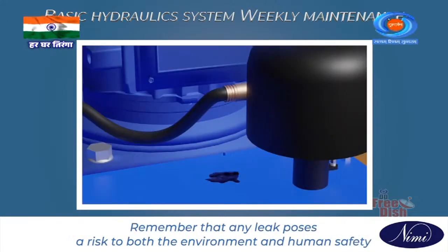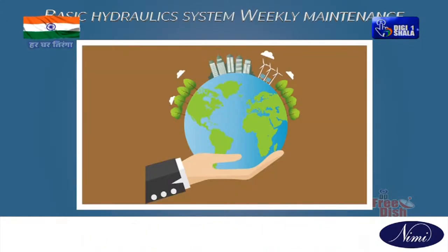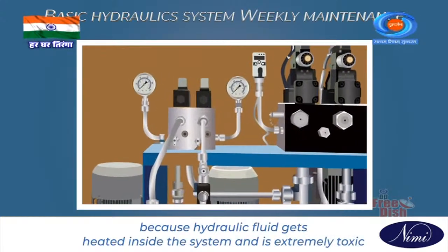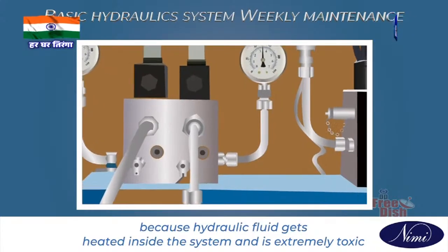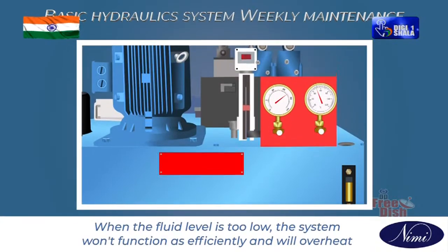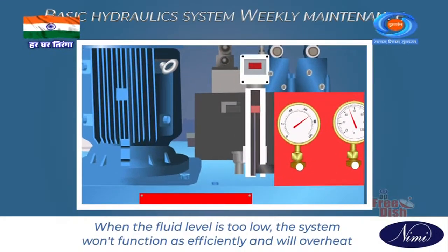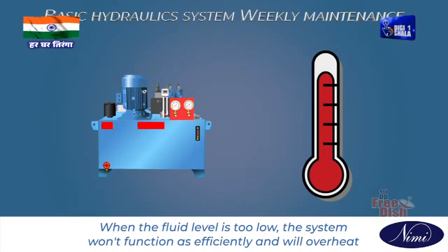Remember that any leak poses a risk to both the environment and human safety because hydraulic fluid gets heated inside the system and is extremely toxic. When the fluid level is low, the system won't function as efficiently and will overheat.